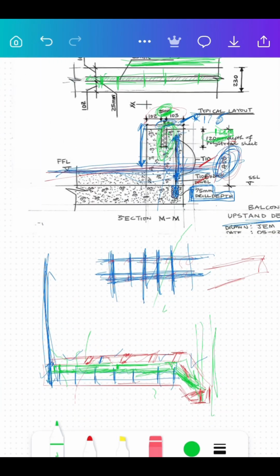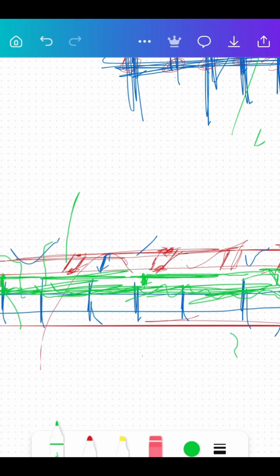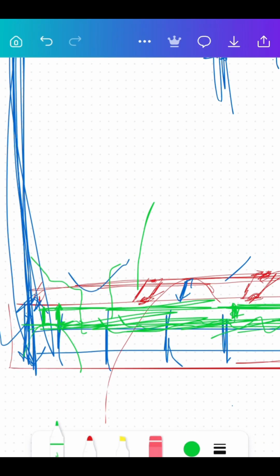So we put it in the perfect middle. We just check the middle of 17.5, and the width of the polystyrene. And once we do that, then we continue pouring our concrete till our concrete reaches the top of this formwork. Remember, the formwork is 40. Our concrete is 40. The formwork is 17.5 centimeter wide. Our concrete is going to take the same shape, the same dimension.